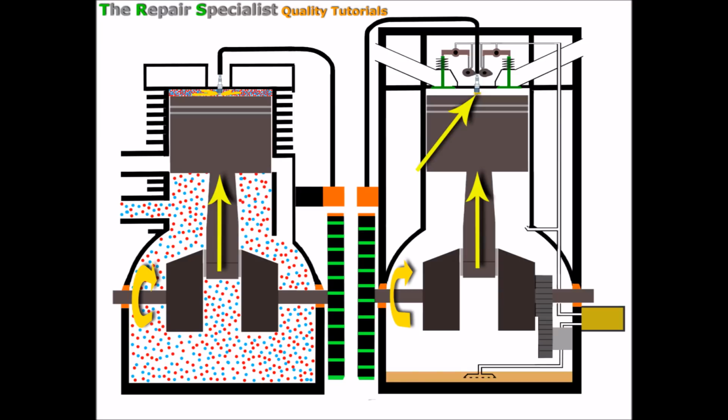So there's going to be a spark whether it's on an exhaust stroke or a power stroke, and that neither provides a benefit or a detriment to the engine. It just happens because of the timing of the electrical system. Some people believe that this extra spark helps to burn up any extra gases that haven't yet been burnt up, and if it does that, great. But in either case, I'm just illustrating here that the exhaust fumes have been pushed out of the exhaust manifold and the exhaust valve is now shut. I'm not saying every last bit of exhaust fumes will be gone from here, but I'm just expressing that this is the point at which they're pushed out.